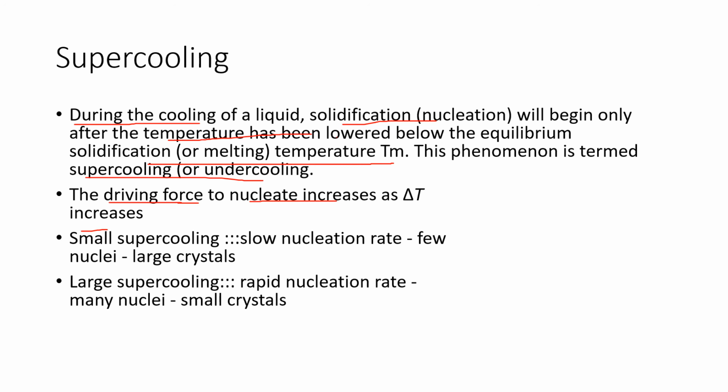So for small supercooling, the nucleation rate is slow and few nuclei are formed, but large crystals are formed. For large supercooling, it is a rapid nucleation rate and many nuclei form, but the crystals formed are small.